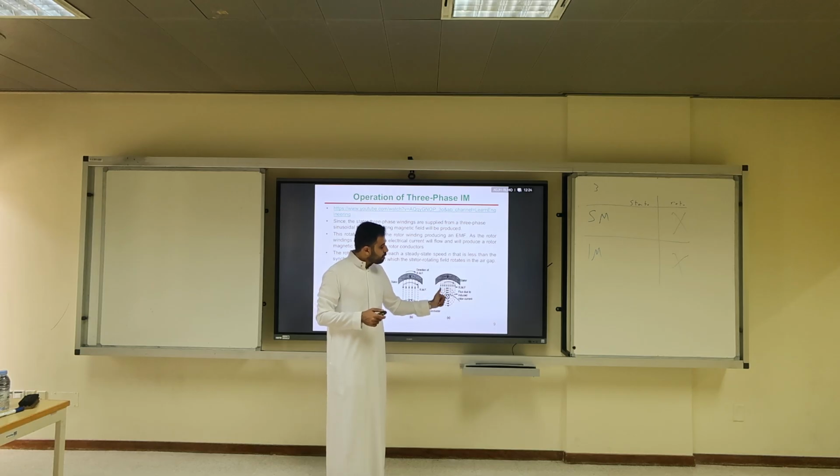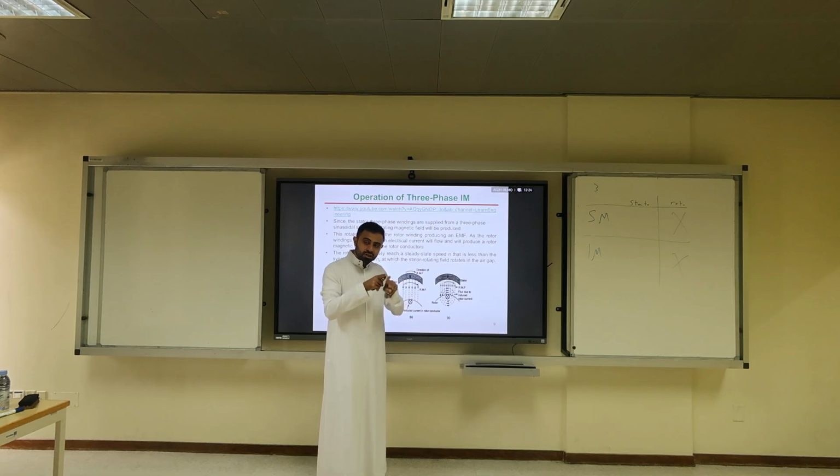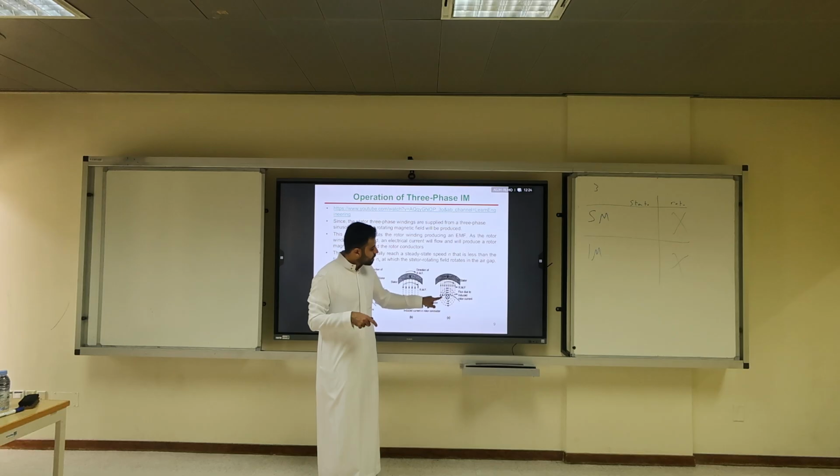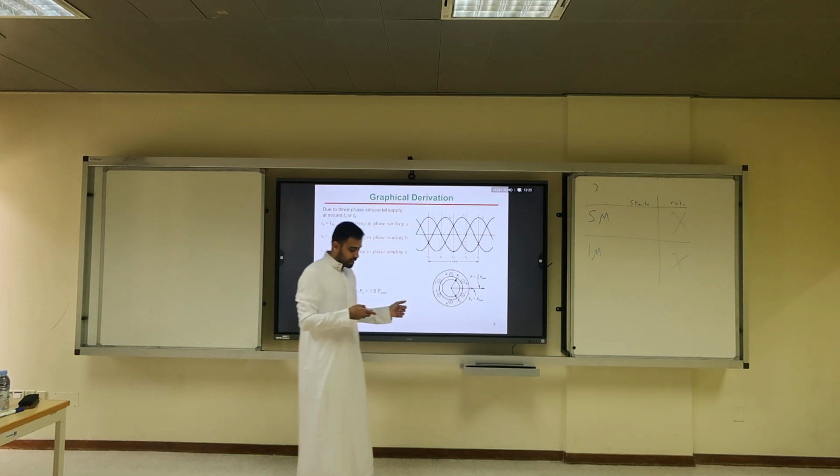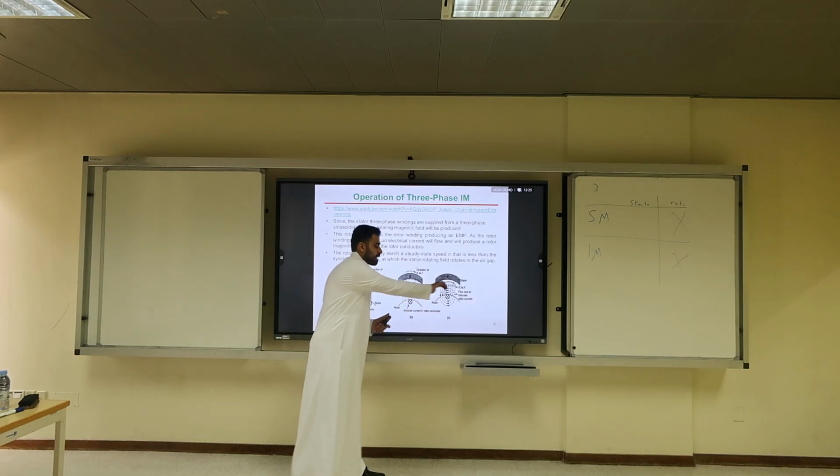So the flux from the rotor cuts the original RMF that is rotating. We get induction of current here that results in induced voltage, that results in another induced magnetic field. The interaction between them, if you see here, for example, you will note that the arrow here is stronger than the arrow here. This one is in direction of the flux, while this one is the opposite direction of that RMF. You see it? The small cable, I have the right-hand rule.